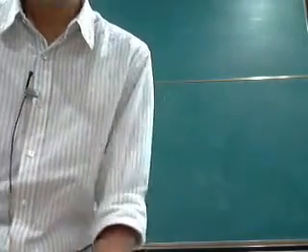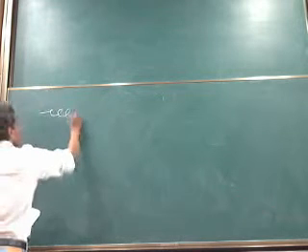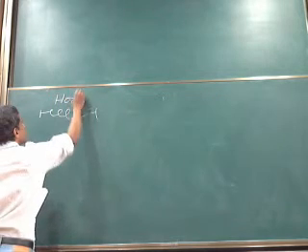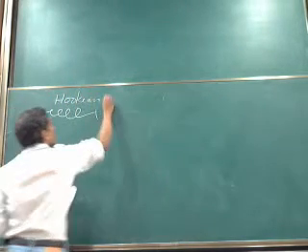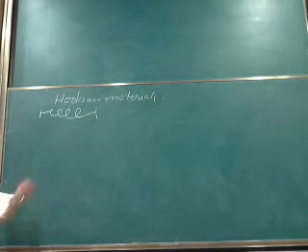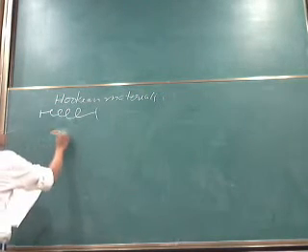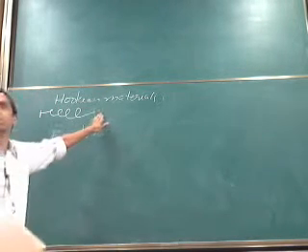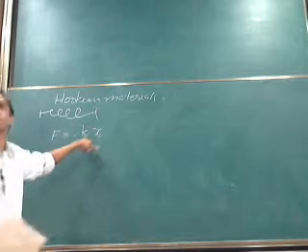Okay. So let me start by introducing viscoelasticity. You are all familiar with simple elastic materials like a spring, for example. If I take a spring and if I stretch it, these are called Hookean materials. Then I can write down the force as F = kx, where x is the distance by which I am stretching the spring, and k is the spring constant.